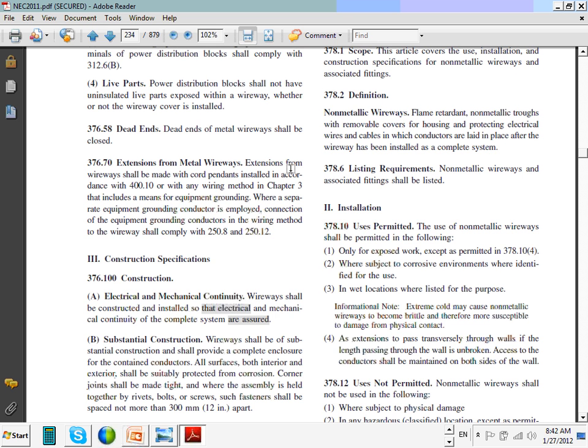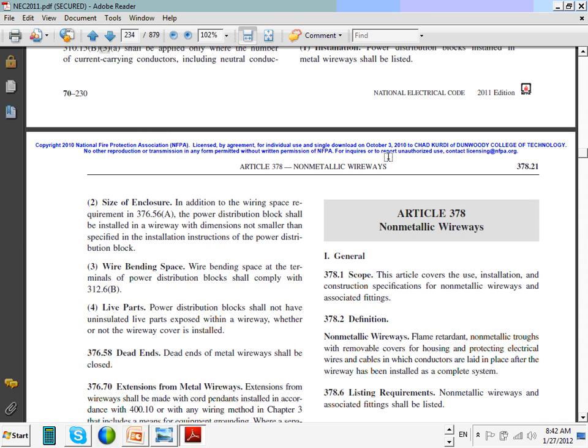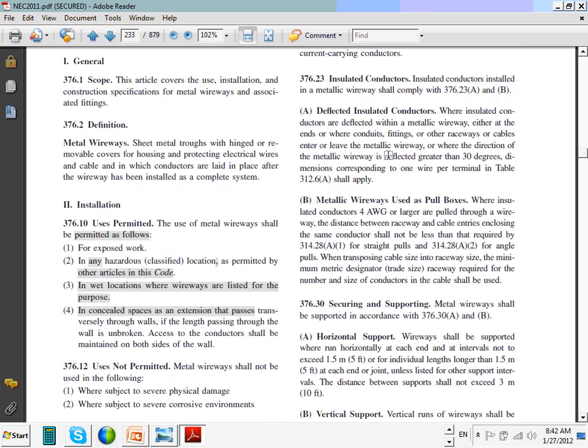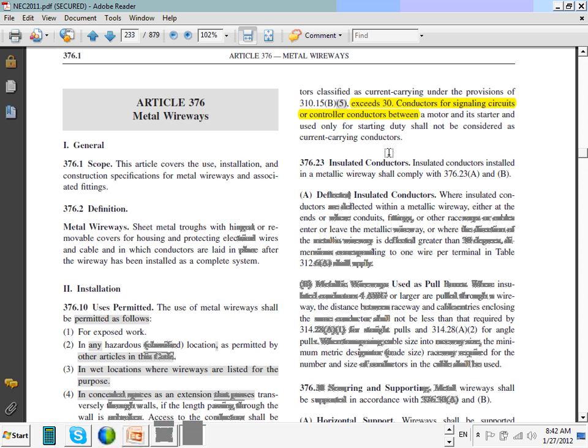So, Chad, to clarify, I'm just reading the definition in chapter 100. Raceway is a collective term. Raceway by itself, not surface raceway, is a collective term that describes multiple conduits and multiple wiring methods. Wireways are a special type of raceway. Good point.